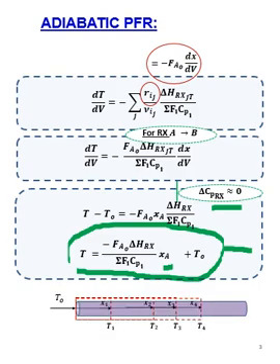So what that implies is that in my plug flow reactor, instead of having a differential equation for my energy balance, if all the conditions I mentioned are true, it is adiabatic, so I don't have the path variable Q in my energy balance, and delta Cp of the reaction is equal to 0, I can have an algebraic equation that represents my energy balance of temperature as a function of X. For each little slice, I can calculate the temperature algebraically as I integrate. Still, I have to integrate over X with a change in volume.